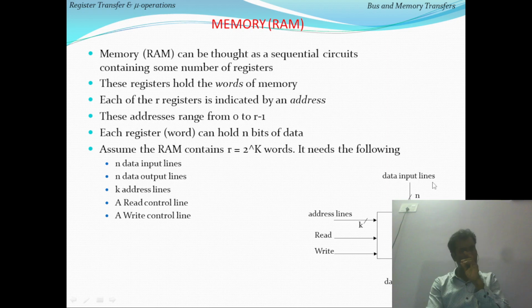Apart from the address lines, this memory has data lines, which are bidirectional: data input or data output, generally in one direction at a time. After pointing to the location, it can access the data. The data can be stored into the memory, or retrieved from the memory, which is specified by the read and write control signals. In a read, the processor reads the data from the memory.